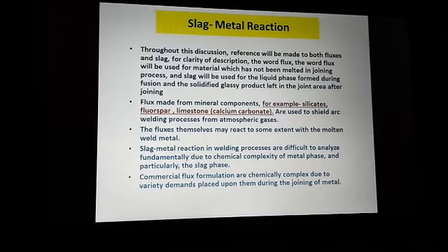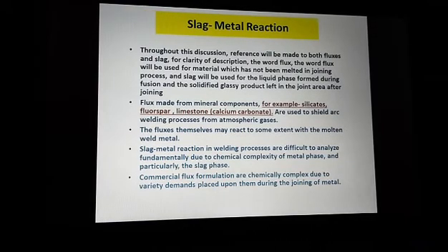Flux is made from mineral compounds, for example silicate, fluorspar, limestone or calcium carbonate, and is used in shielded arc welding processes to protect against atmospheric gases. The flux itself may react to some extent with the molten weld metal.